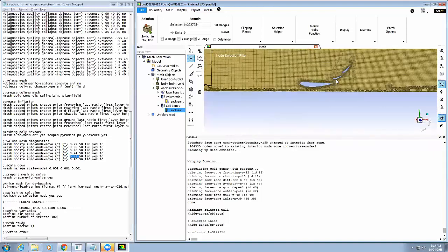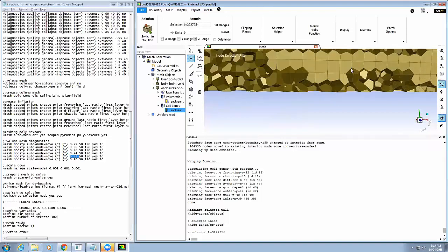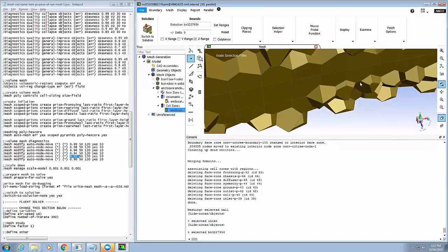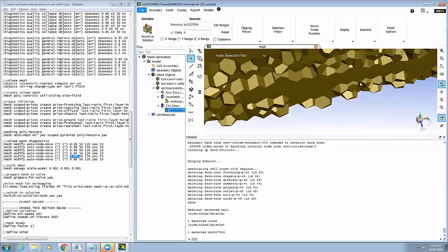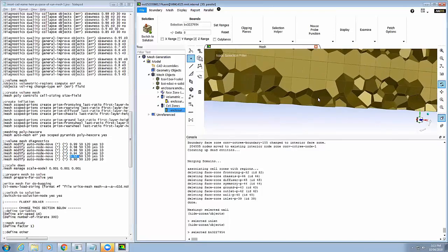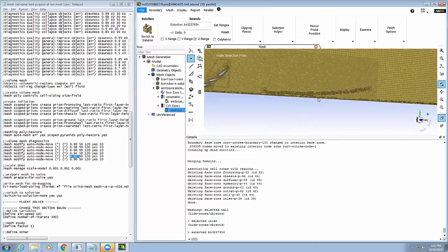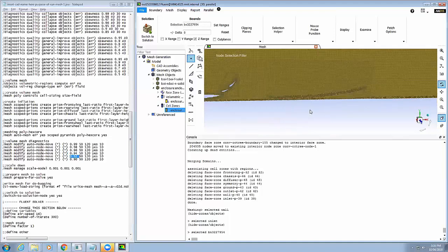Yeah, and that's pretty much it, right? And then you normally have inflation on the floor. You can see this clearly doesn't have inflation. Why would you have inflation on the floor? You'd have inflation on because you want to capture the pressure gradient. So having just a couple of layers just makes it uniform and makes it nice. Okay. Right? But then that would run all the way along the floor. Yes, it would. So that you can maybe. Yeah. Okay. Yeah. I mean, look, it's difficult, right?